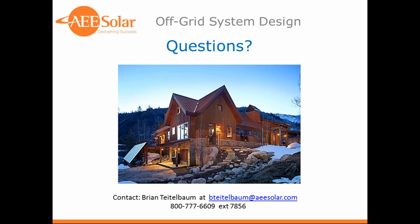All right. Great question. The next one we have is: when you were doing the MPPT charge controller calculation, are you using VMPP or VOC? Good question. You use both, actually. You have to use the VOC when you're looking at the limits of the charge controller. Most of the 150 volt charge controllers out there will actually stop operating at about 140 volts DC, and they can be damaged if voltage is over 150 volts DC.